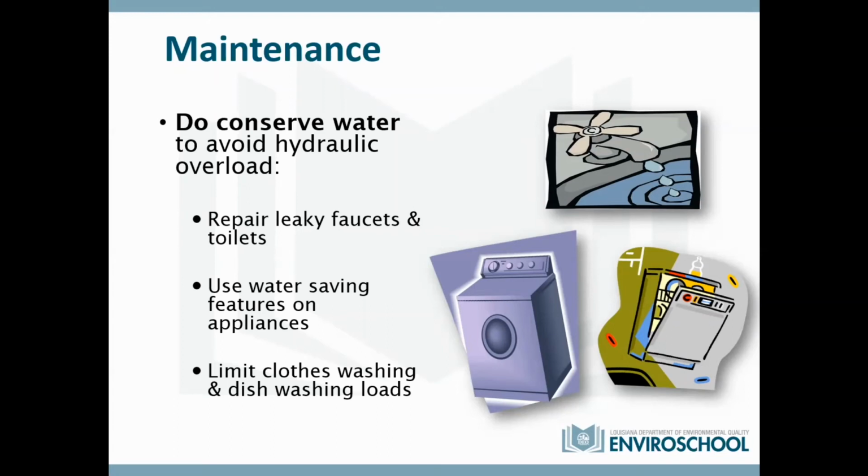Some other examples, again, we've heard of people having a Super Bowl party and a ton of people there and they're all using the one or two toilets and something goes wrong. Sometimes it's basically just too many people using the system and it's hydraulically overloaded. The system can't keep up, and sometimes you can end up getting a smell because of that. So those are things just to be thinking about.